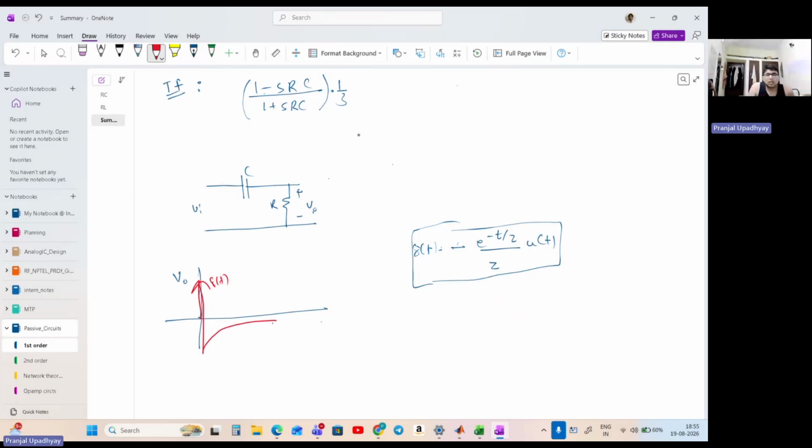Okay, so physically, what is happening in the circuit is that the moment we feed an impulse, this capacitor won't allow a sudden change of voltage across it. Since the capacitor won't allow a sudden change of voltage across it, if this is an impulse, this will also be an impulse. Alternatively, this capacitor will allow a high frequency change, and at the output we'll see an impulse, as we can see from this portion of the output. After t equals 0 has elapsed, we must understand that this capacitor will get shorted because the output is now 0. And this is the scenario we will be posed with.